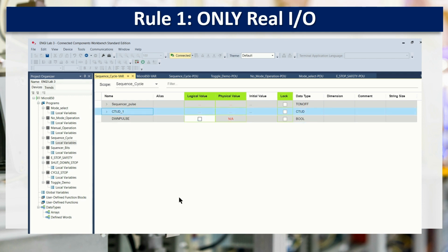So in most situations, you're not going to ever need to manipulate and lock on an internal bit. If you do, you'll have to do it in logic, and there are a number of ways that you can do that. To permanently turn something off, take an unconditional rung, turn an output on, then use the NOT bit in front of it, and then that internal output's never turned on.